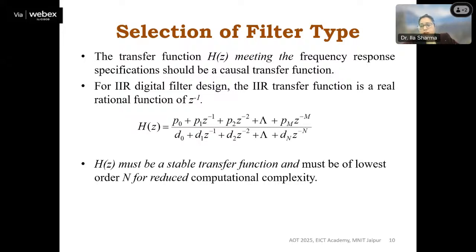On the other hand, when we compare with FIR, FIR will always give a linear phase. That is the property of it. And it is also stable. But when we look at complexity, there is the requirement of the filter order. As I just told you, it defines the filter order, and based on the filter order, the higher the order, the higher the performance, you know, right?